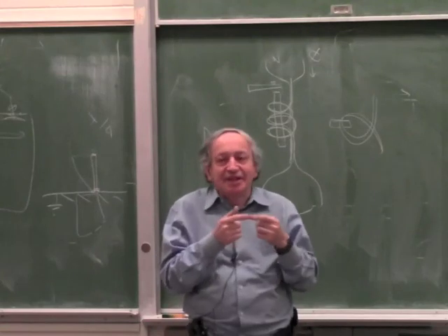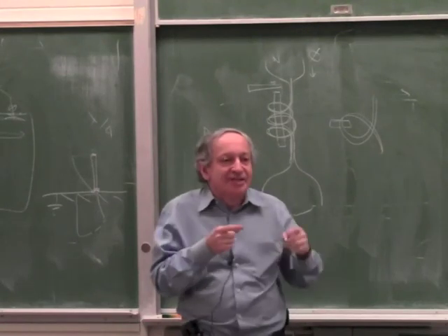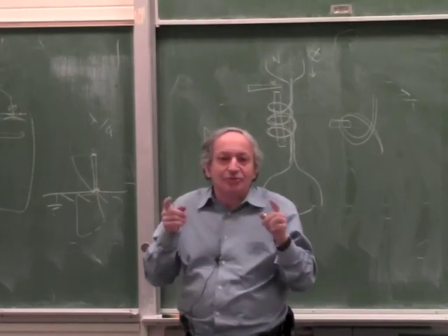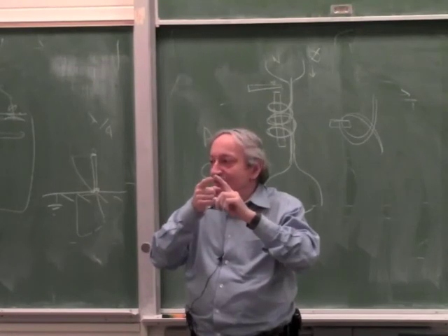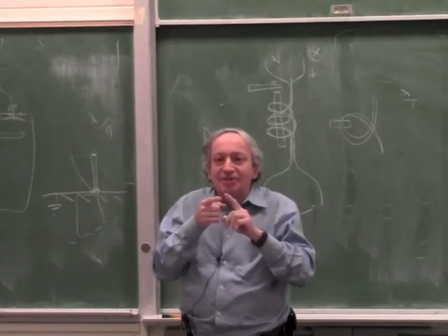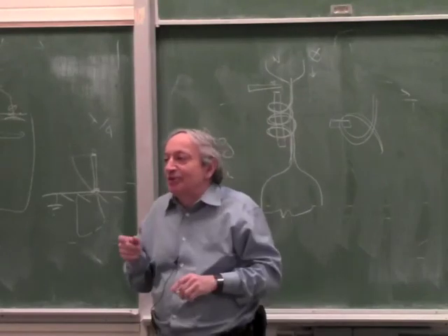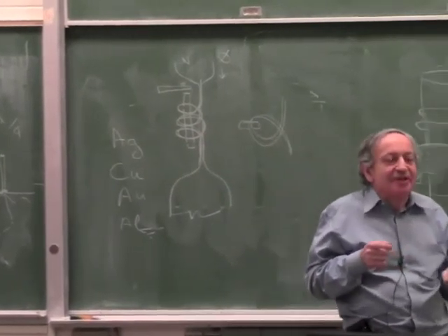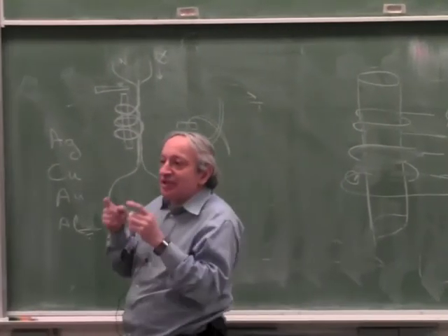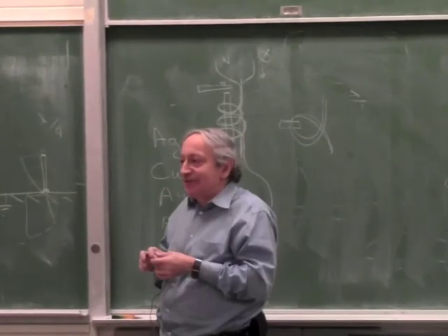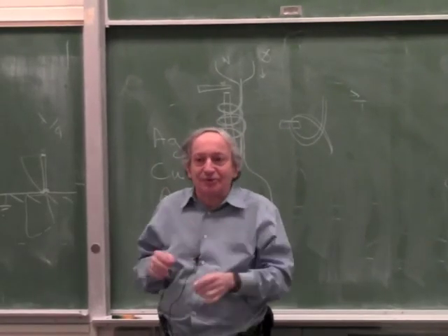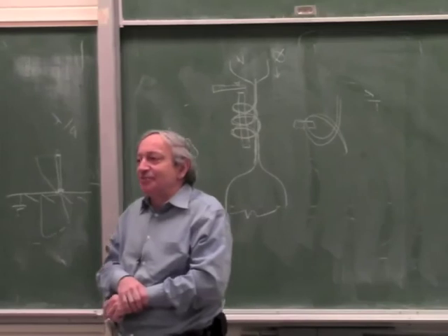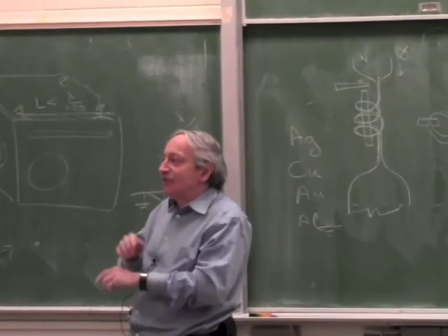Every other metal needs a little bit of pressure, because every other metal has a layer of oxide on it, which could be an atom thick. So if you just take two wires and touch them together with no pressure, even two copper wires, unless you apply some minimal pressure, say a gram, there would be no electrical contact, because there is some oxide layer, hydrocarbon layer. Gold is the only metal which at a very light touch gets full contact. And corrosion resistance means it's never going to corrode. So the second reason is gold is the best material in making good contact at low force.